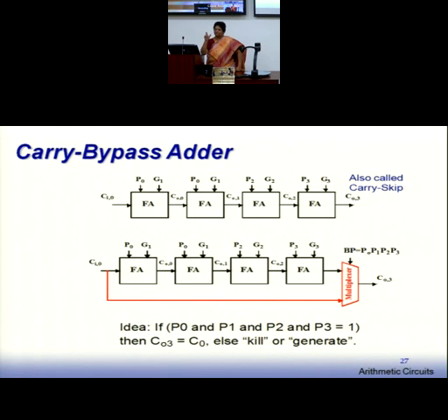They are saying, look at the 4 blocks, 0 bit, 1 bit, 2 bit, 3 bit. Look at 4 bits together, and then see if there is a carry generate. Then why should you wait for 4 positions to be computed? Because in any way carry would be generated out of it, because all generate functions are 1. So look at the generate function of each one of the 4, add them together and get me the carry out, because anyway it would be generated.